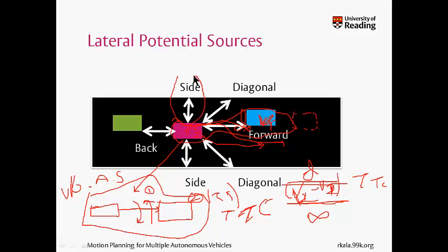The second that I take is this side. So imagine you are the vehicle out here. After this distance, there's some obstacle. We do not know what it is, but there is some obstacle. And obviously, I need not discuss the direction. You'll obviously turn right. And you'll turn right by a factor inversely proportional to the distance. The more the distance, the less you turn. The less the distance, if you are somewhere like this, you need to take a very sharp turn. It's completely the opposite for this.